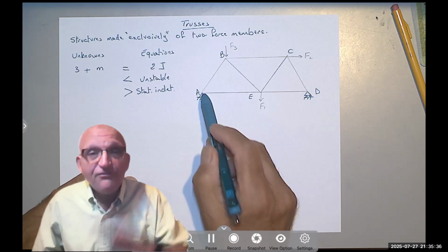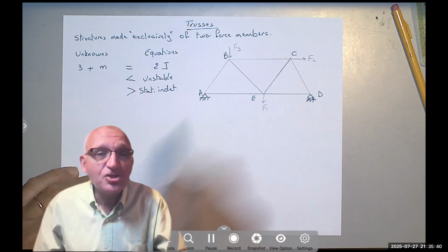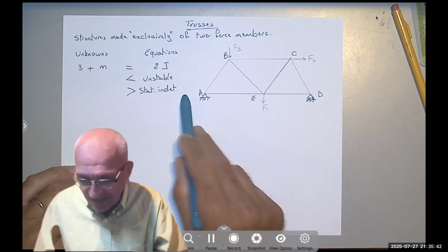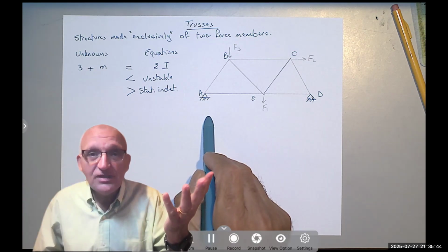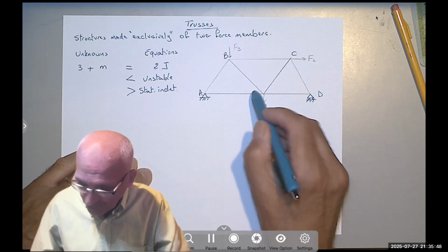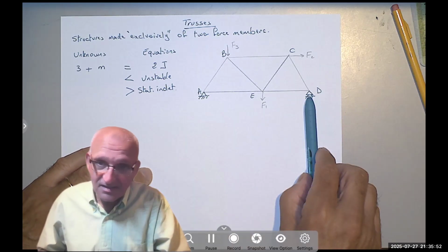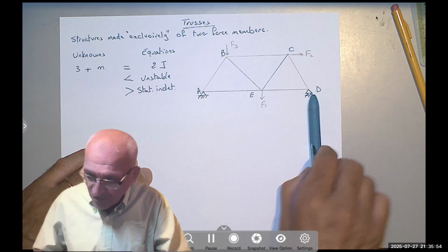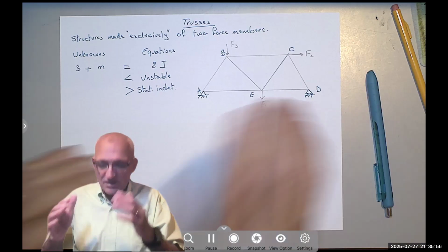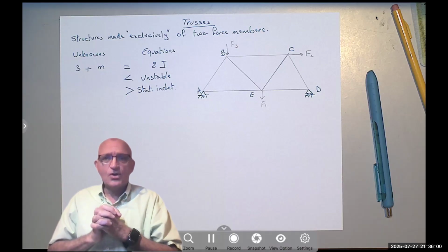Here I have 4 unknowns, 2 members and 2 reaction components, because that's a pin, it has an X and a Y, and I don't know either. Here I have 4, 1, 2, 3, 4. Here I have 3: the Y, because this doesn't have an X, the Y for the roller, and the member forces. So, oh my God, I'm stuck. I cannot start. Or can I?